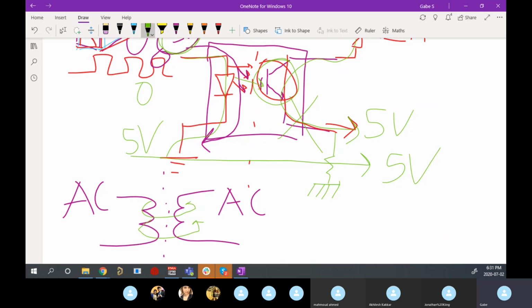Often what you can do is send your AC signal to the transformer. It will show up on this coil as well with whatever turn ratio you have. And then you can keep going to wherever you need to go. And this is completely isolated. So you can have different transformers and different opto-isolators with different isolation ratings. Usually they'll be in the kilovolt range, good enough to isolate 1 kilovolt from end to end, for example. So if I had one side at 5 volts to ground and the other side at 1,005 volts to ground, it'd be rated to that much. For our systems, we don't go that high, but you'll see a rating of that usually.